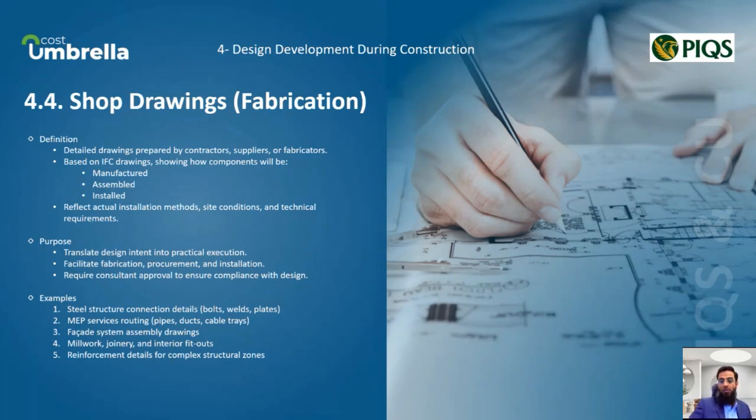Shop drawings are submitted for review by the design consultant, not for redesign. It's not for design purposes, but to confirm they are aligned to design intent. Only the consultant will make sure whether the shop drawings are aligned with the approved design or not. These drawings are critical for procurement, prefabrication, and sequencing the work on site.